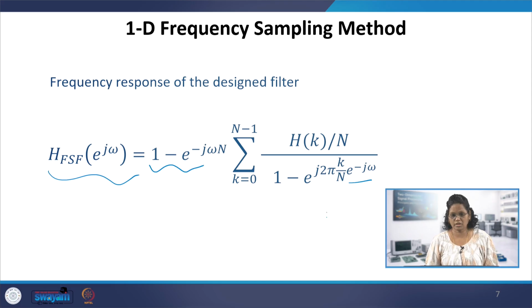The number of resonators that can be added in the structure depends on the peak response we want for the filter design, what frequencies are to be passed, what frequencies need to be in the output, and what frequencies are to be attenuated. So k would be chosen depending on that, and adding all the resonators together and multiplying with the comb filter will give the frequency response.